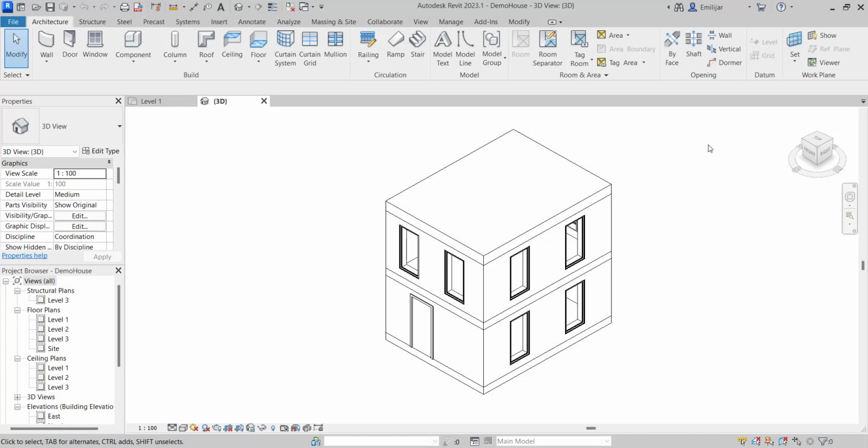We're going to firstly start in Revit, and this is just to make sure that you're exporting your BREPs right. So firstly you want to be in 3D view, then you want to make sure that the floor and walls are not overlapping. This is just so the plugin works.